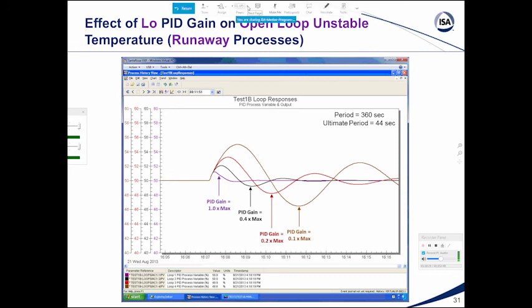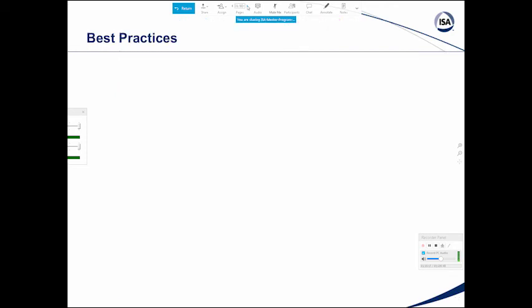By maximizing the gain. Some of the gain settings don't give you the true gain. The true gain in a well-designed, well-tuned valve positioner has a gain approaching 100. And that means you really don't need integral action in the positioner. In fact, it causes all kinds of problems. And so the offset is very tiny, and really has no consequence. It will be corrected by the process controller. So don't ever turn on integral action in a positioner. That's a subject in itself.